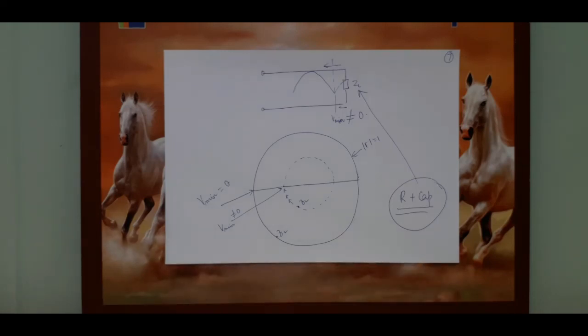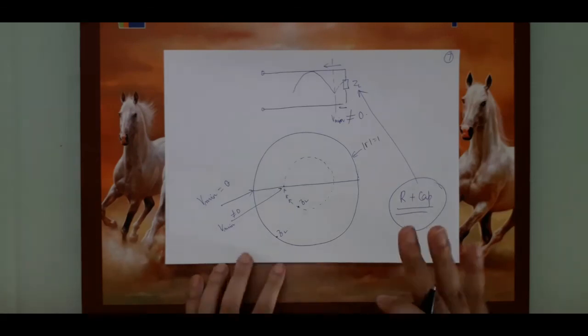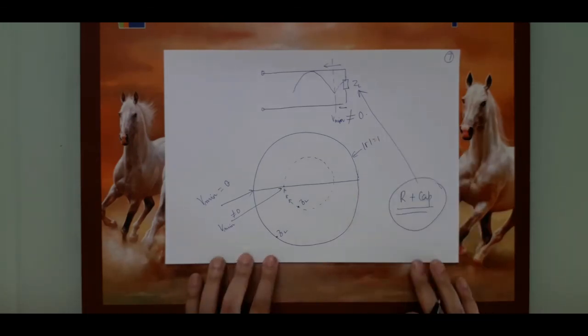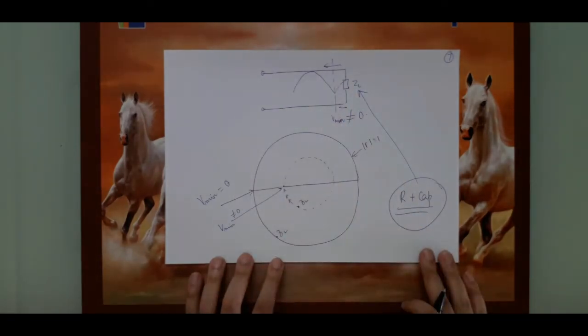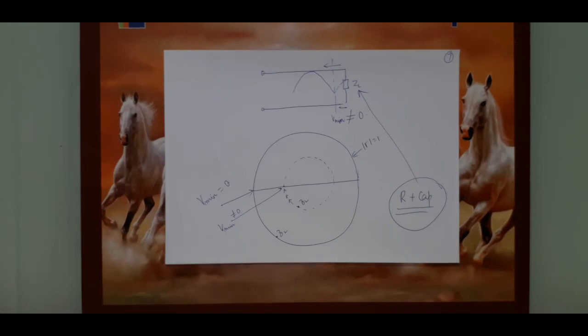So today we saw a number of applications of transmission lines, including realization of L and C individually or in the form of LC resonant circuits, and also we saw one very useful technique through which, if we look at the voltage maxima or minima along the line, we can identify what type of load it is. So with this, we shall stop here.